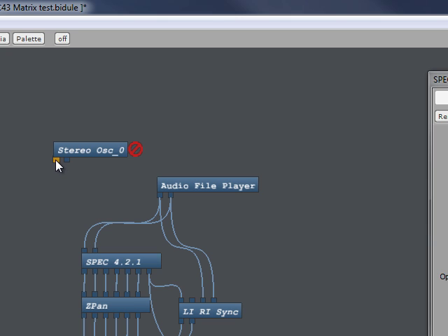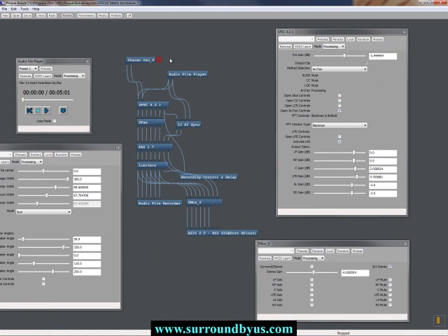So the way you connect things is click on a pin and drag to another pin and let go, and it makes the connection for you. There's also a shortcut. If I hold down the control key before I click and drag, then it will try to make all of the connections that it can at once. So that's a nice shortcut. We're actually about out of time for this chapter, so we'll pause here and take it up in the next chapter.